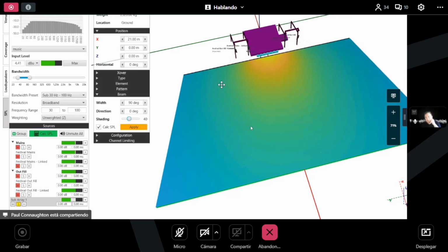Setting the shading to 0 will allow for maximum shape with no gain level offset throughout the array, whilst turning this slider up towards 100 will start to add gain and shade throughout the array, which will sacrifice your pattern shape and the control for maximum output.